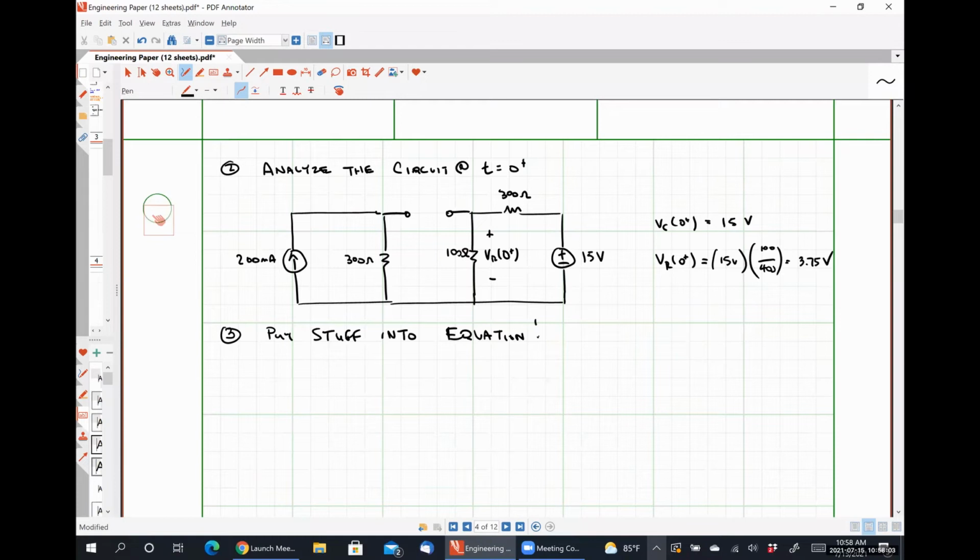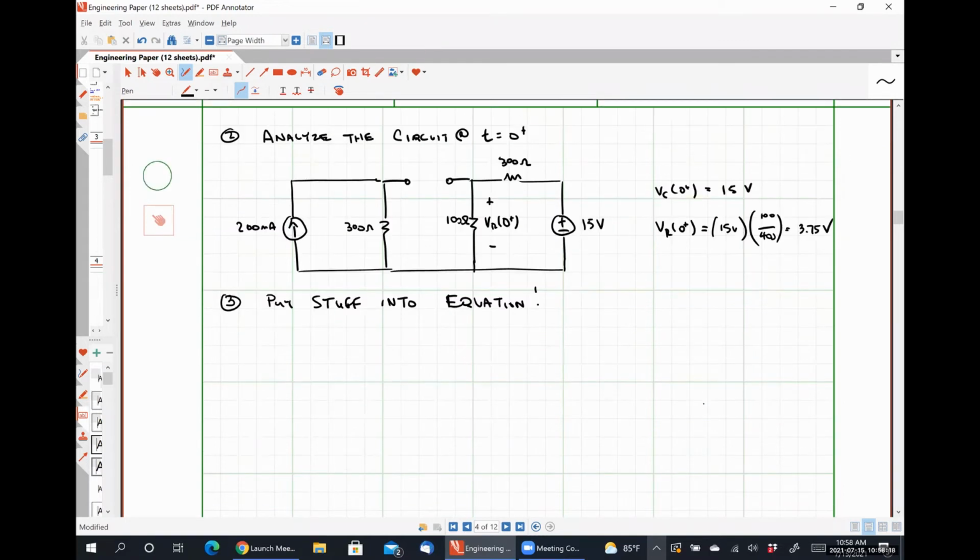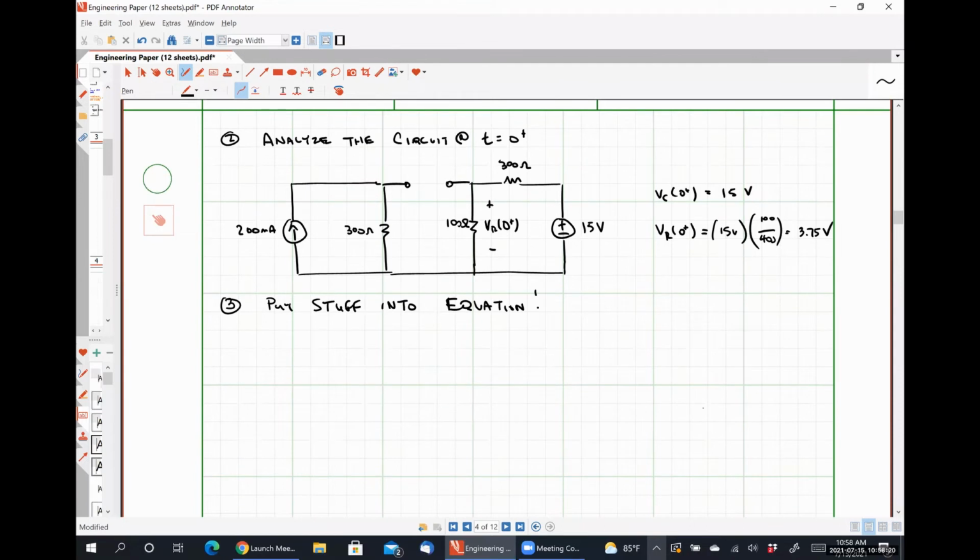We are going to need to know the equivalent resistance that the capacitor sees, right? In a previous problem, there was only one resistor connected to the capacitor, so that was pretty trivial. So let's formally talk about how we find that equivalent resistance, okay? As we discussed in class last Tuesday, we are looking for the Thevenin equivalent resistance connected to our capacitor, which means we need to be looking at a dead network during the transient condition.